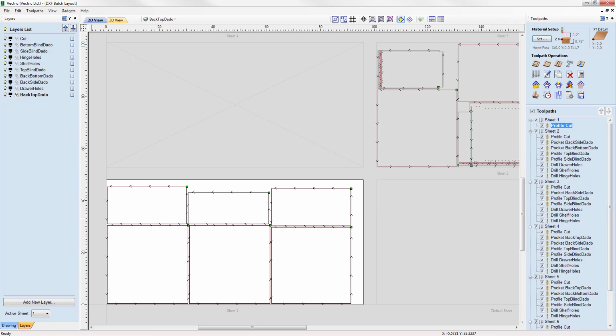You can see that by taking the time to create the toolpaths and associating them via their layers, we've managed to save a lot of time when creating toolpaths for sets of vectors in similar jobs like we have here, whereby we can import the original toolpath template and simply apply it to all of the sheets that have been created by the nesting feature.